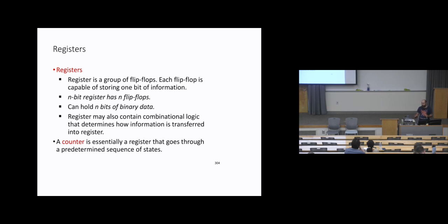So now we know first how to do the basic logic diagram based on the transistors, based on PMOS or NMOS or CMOS transistors. So we know how to do the basic logic using NAND, NOR, and NOT gates, right? Then after that, we know how to implement AND and OR from NAND and NOR. This is in hardware, right? Then we can create our chips. This is the chip AND, this is the chip OR.